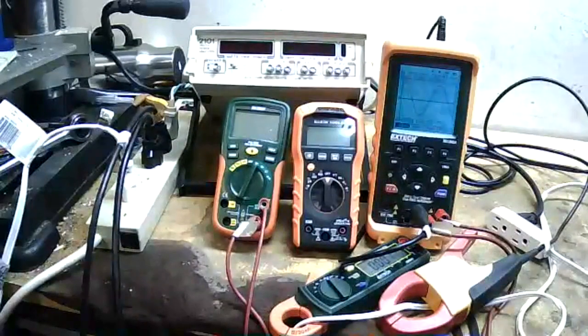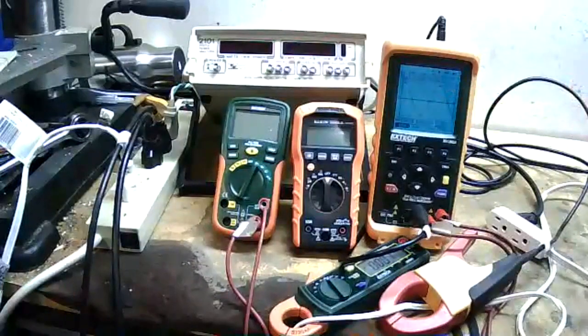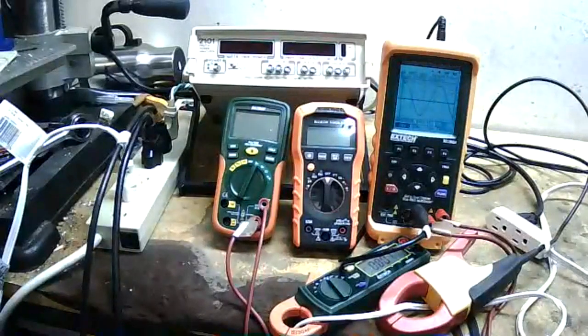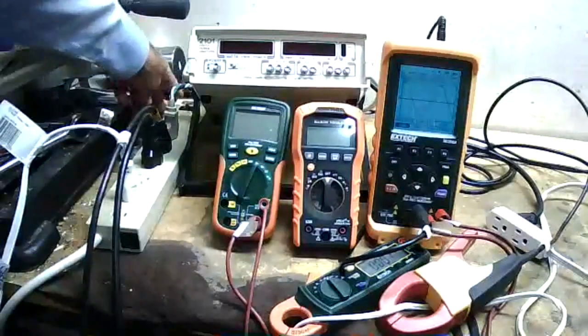I think we can see that. You're seeing the voltage waveform, the 120 volt waveform. Interesting thing about it, when we do power factor, I'll take a picture of this so we'll have something good to work with. The top of that sine wave is flattened off. That's because of all the DC loads we have in this house. And a DC load, any electronic load, starts off with a rectifier and rectifies the AC to DC and then powers the load. So that's any electronic load. Now, that's not what we're here to talk about today.